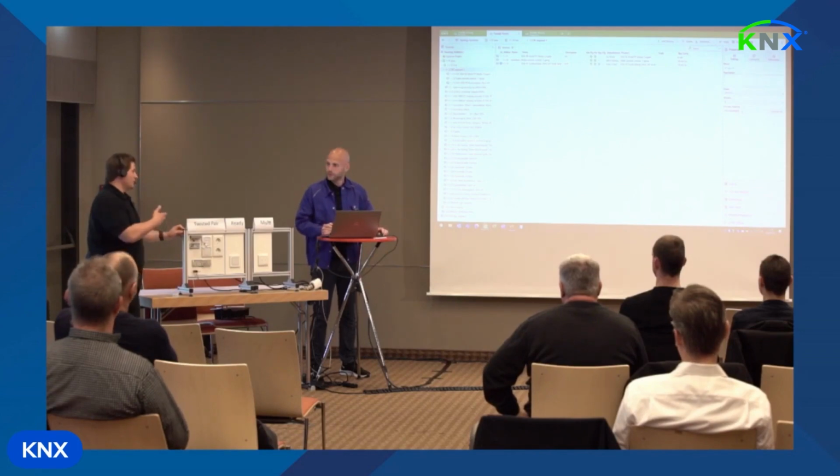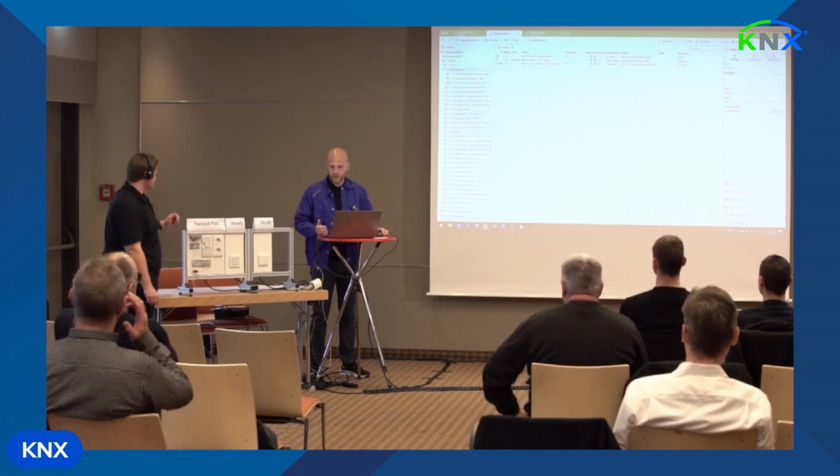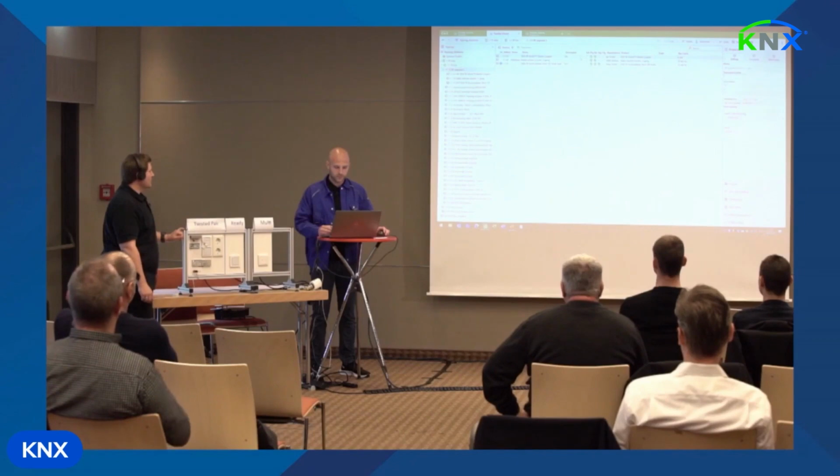But still, the individual addresses have changed. They had a 1.2 address from the line. Now they're inside a segment of the 1.1 line. So the individual addresses still need to be programmed. Like ETS tells me here as well. So please go on and select these devices.